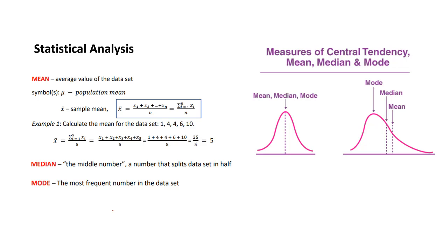And if we are taking the readings from a tester, then we need to check whether the readings are coming accurately or not. For that case, we do the statistical analysis. Suppose we take 10 measurements, and then we take an average of that. And then we check the range or deviation also.